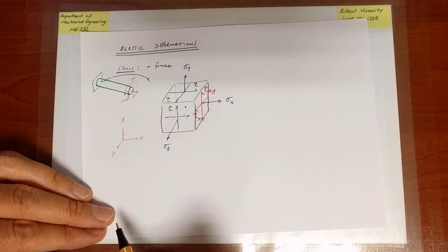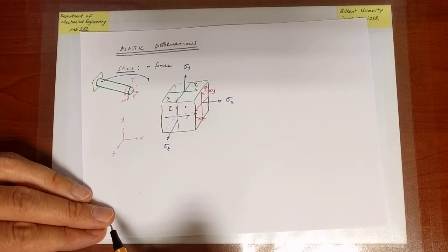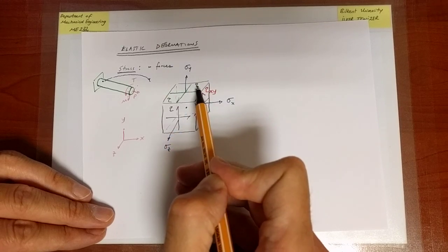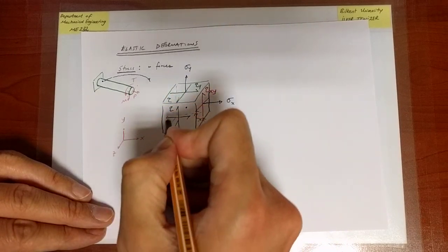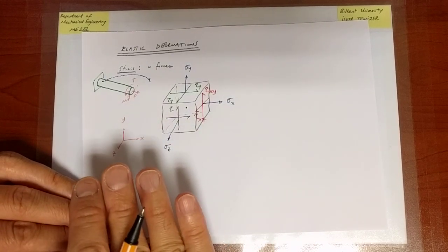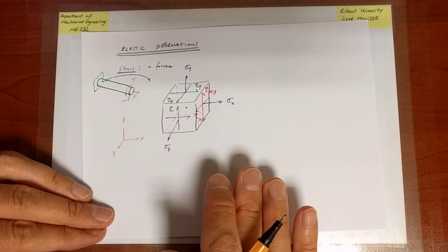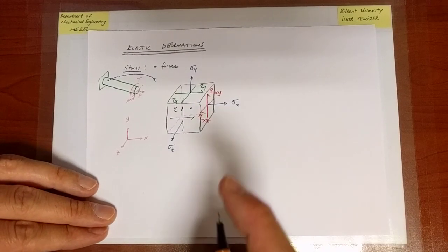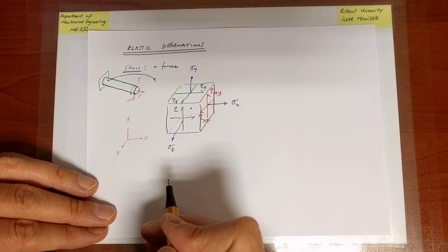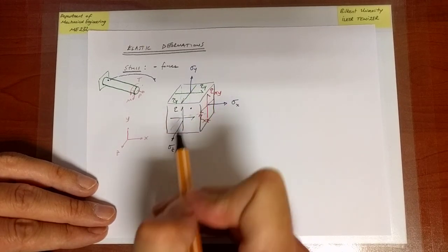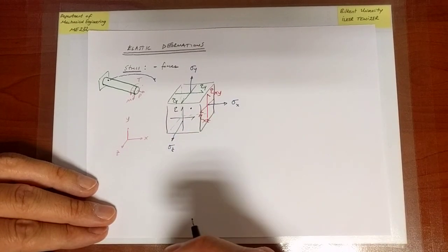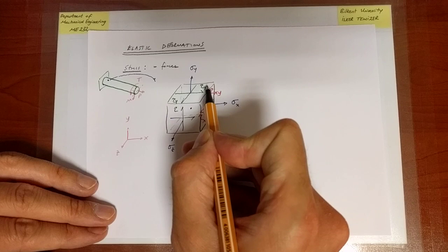So what shall I have for the green components? We are lying on the plane with normal y. So there's a normal stress sigma y. That's the index that we can immediately attach to the shear stress. This already will eliminate a certain possibility for making an error when we are indicating the stress components. So immediately attaching the normal component index puts us at a certain level of safety, if you like, with respect to making an error.